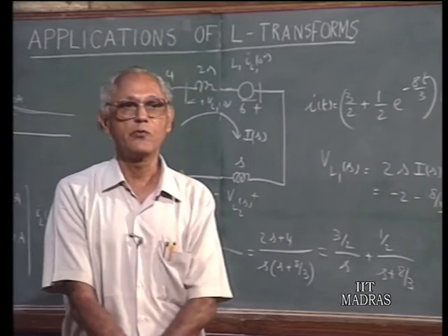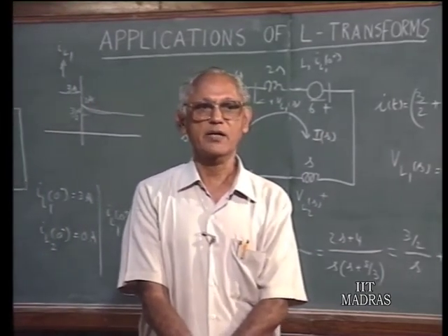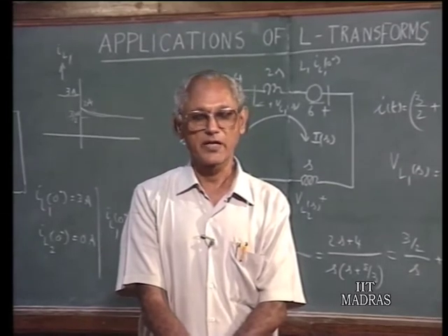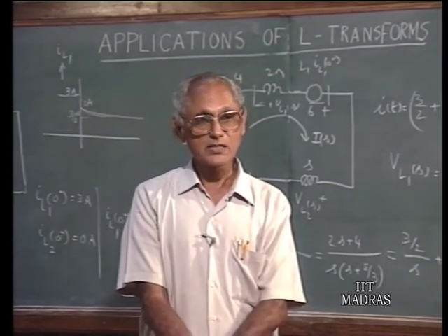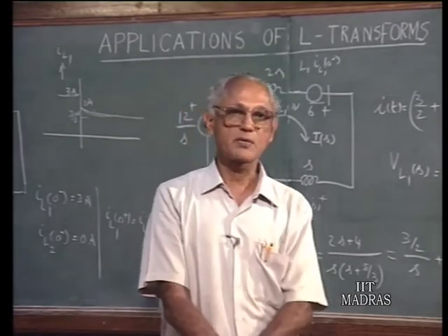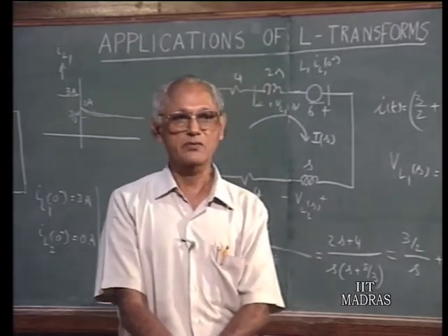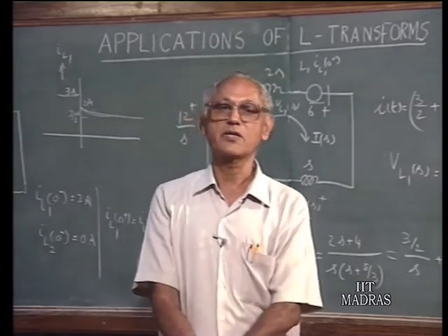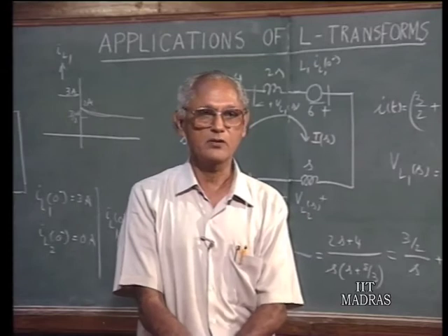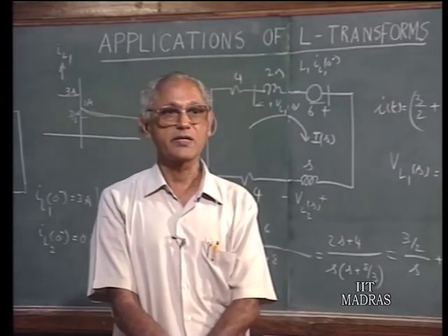Therefore, you do not have to evaluate separately the arbitrary constants that you have to do in the case of differential equations. And this is very important, because if the order of the system, the number of reactive elements becomes large, suppose there are 4 or 5 reactive elements and you have a 4th order differential equation, then you need to know 4 initial conditions, not only the initial value, but the values of the first 3 derivatives.